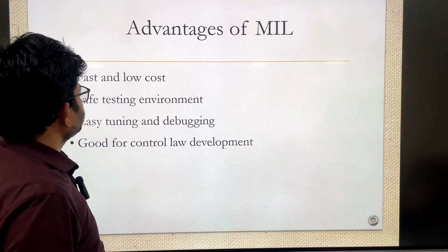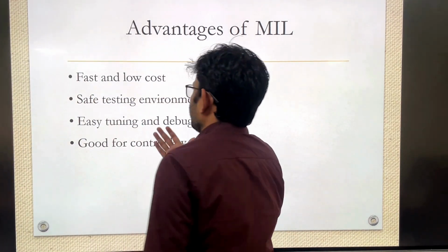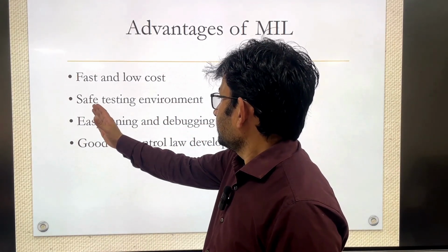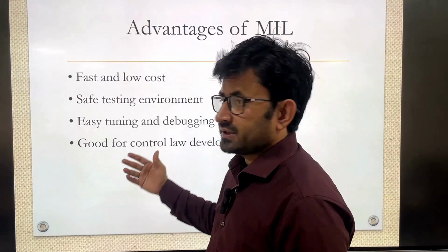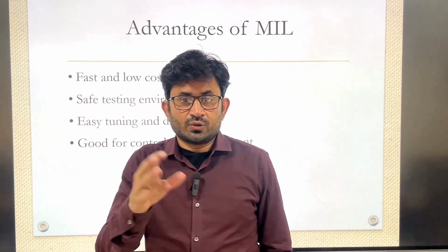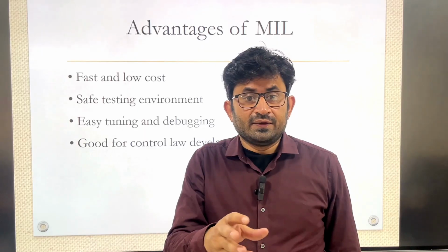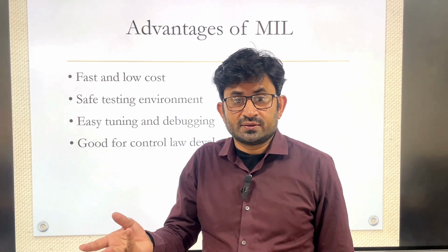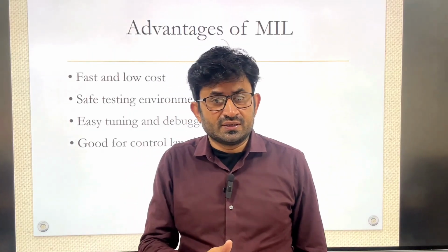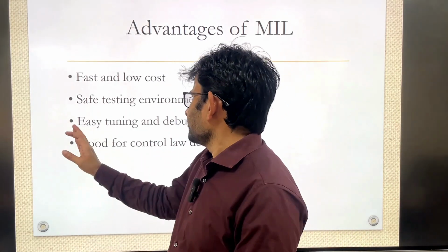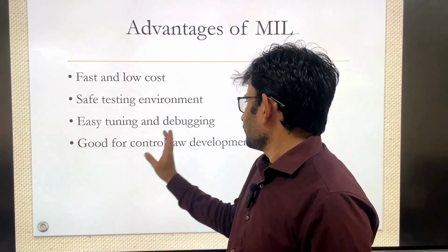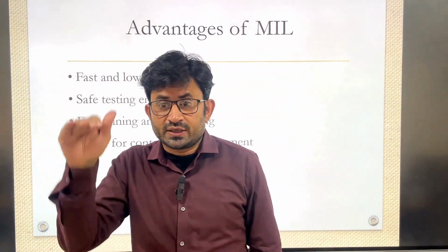And what will be the advantage of MIL? Of course, fast and low cost, because everything is in software only. And then a safe testing environment. Yes, it is of course safe. So whatever you can model, sensor, controller, aircraft model, if you want to change anything, if you want to include non-linearity like ground effect, rotor interaction with the wing, anything you can model in Simulink and you can test. So a safe testing environment. And easy tuning and debugging. If anything is wrong, you can debug.